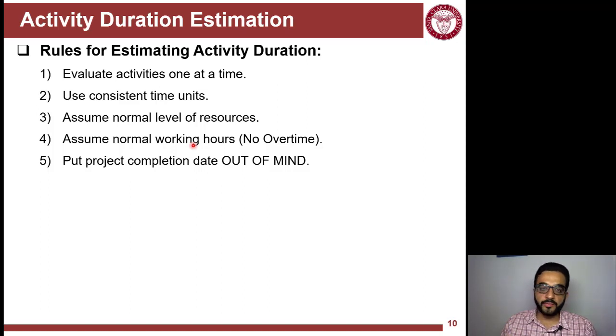Also assume normal level of resources. So don't overstaff your site. Don't think I'm going to use 10 cranes. Assume a relaxed method of construction, and also assume normal work hours, no overtime. Just use the regular time, and put the project completion date out of your mind for now. So just think about a relaxed way of constructing that.